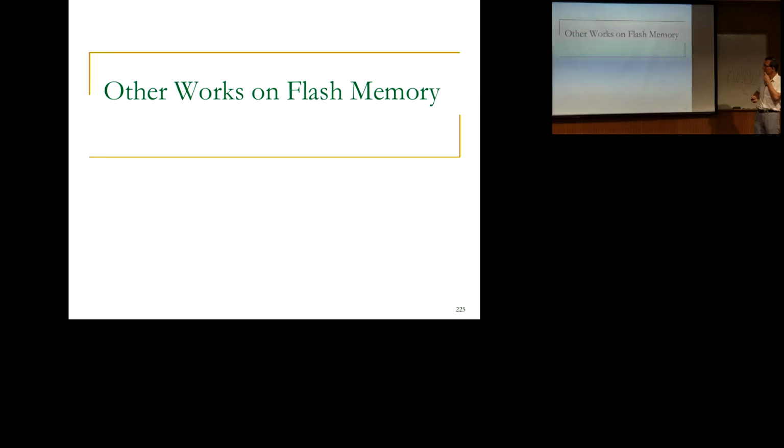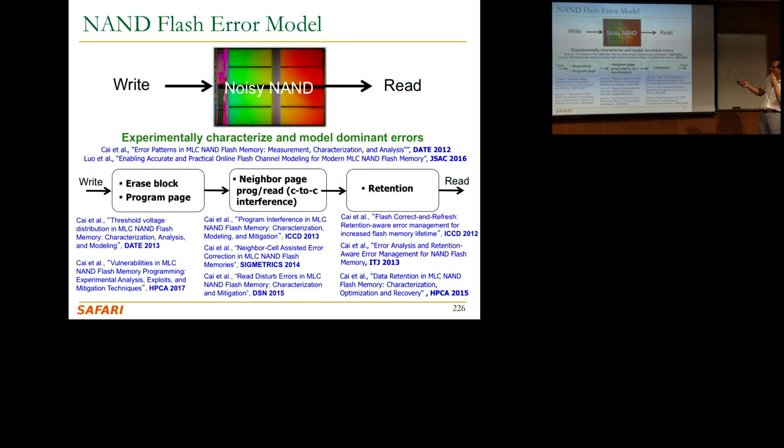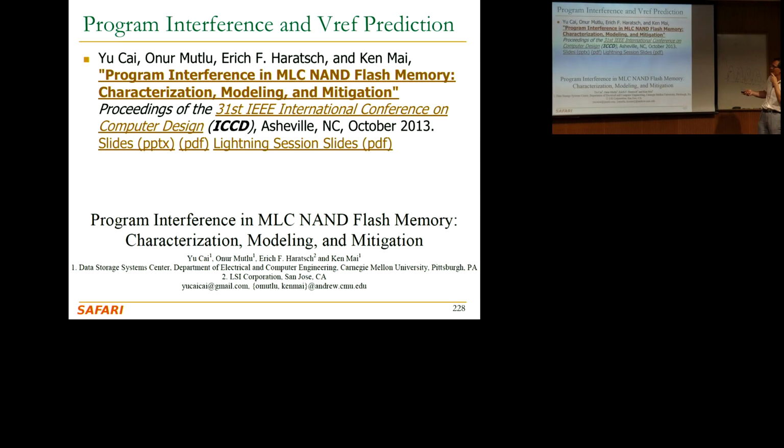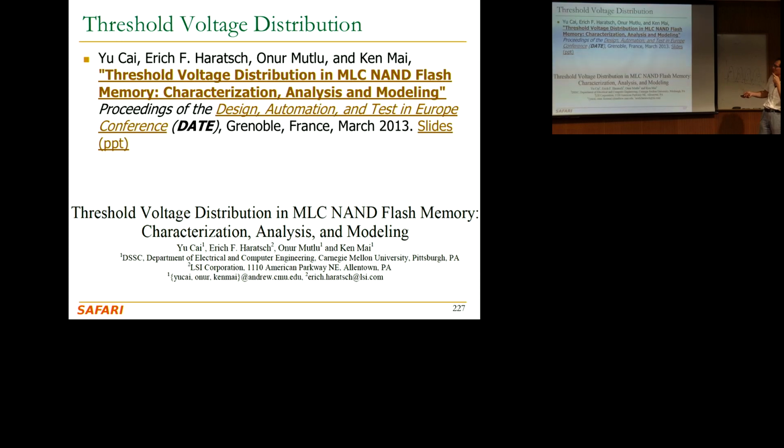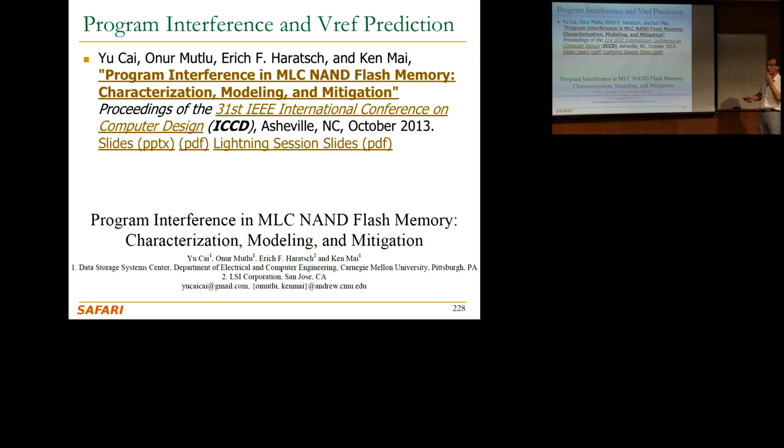This is not moving. So I think there are a bunch of other works that I'm just going to recommend. We don't have time to cover them. But certainly there is a lot here. I think it's a fascinating area. We've studied threshold voltage distributions, which is really interesting. And you can predict threshold voltage, how they're going to shift. You can model them. As a result, you can shift the read reference voltage, as you mentioned, based on your predictions.